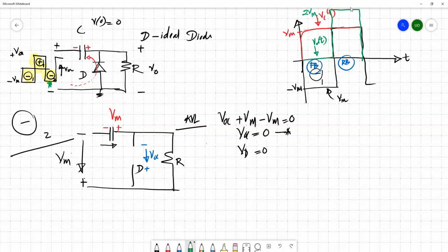So now we should identify if this diode is forward or reverse, because if the diode is reverse, we can simply conclude that there won't be any current flow through this one. If it is conductive, then the diode should be forward biased. Now we'll apply Kirchhoff voltage law and find that the voltage across the diode should be zero during the second negative cycle. So for the ideal diode, we claim that VD should be greater than or equal to 0 for forward bias, and VD should be negative, or less than 0, for reverse bias.